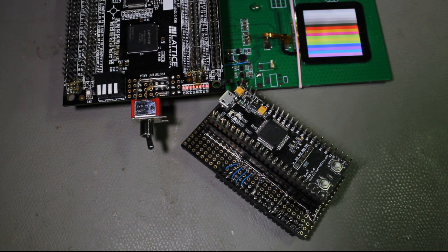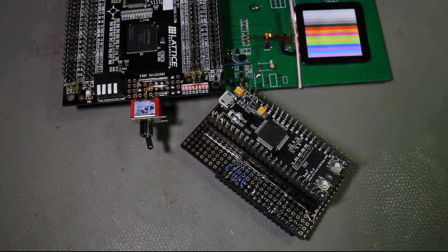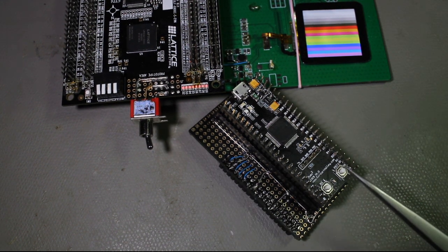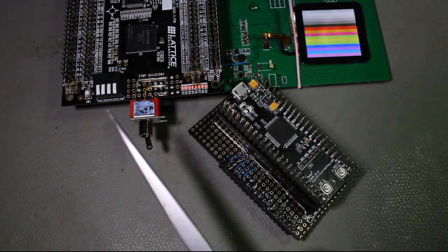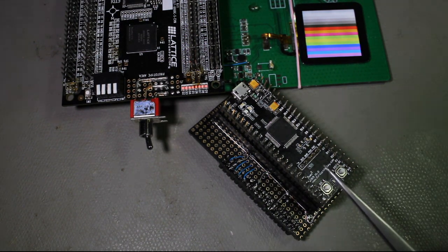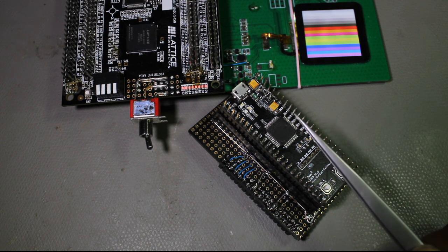So even that 50 MHz is not 100% efficient, so there are some limitations. The primary limitation in this whole USB setup right now is the SPI data rate. The FPGA system can easily achieve the full 60 FPS that the display supports, but the primary limitation right now is the SPI, and how I have implemented the USB.